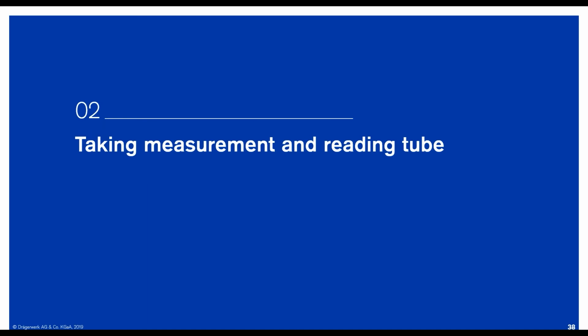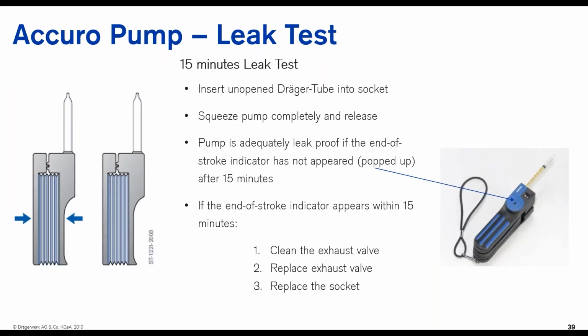So for the Accuro Pump, before you do any test, this is our recommendation: you need to do the leak test. This is a very important thing to do. This is to ensure there's no leakage with each stroke, so the volume of air taken in by the Accuro Pump is correctly within the specifications. So how do you do the leak test?